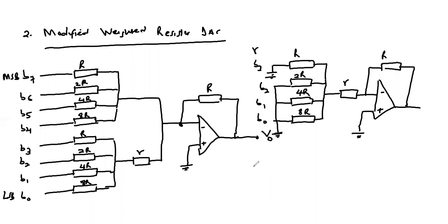Then we know that the current contribution between bit 7 and bit 3 would bear a ratio of 1:16 if the DAC is unmodified. So the introduction of the resistor small r should not interfere with the ratio of the currents between the most significant bit and all the other bits.